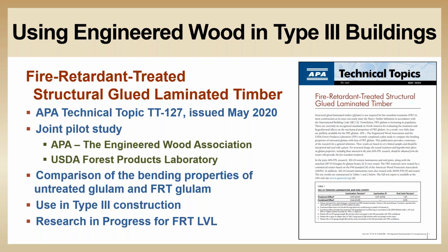And recently, APA published a technical topic summarizing the results of this pilot test program, examining the structural properties of FRT glulam. We did find that the structural design properties were affected by the actual treatment on the glulam. So be sure to evaluate the product with the design capacity reductions and recommendations, which should be obtained from the wood treating company, as the reductions can be very significant, as was demonstrated by this testing.